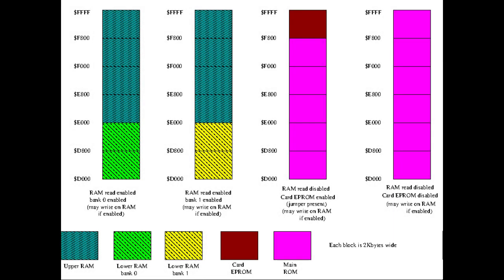Okay, first let's see how the additional 16 kilobytes of RAM will be mapped on the 6502 memory space. As you may know, the 6502 can only address 64 kilobytes of memory at the same time, because it has only 16 address lines. So on an Apple II, onboard RAM, which is up to 48 kilobytes, starts at 0 and ends at BFFF, which is 49,151 in decimal.